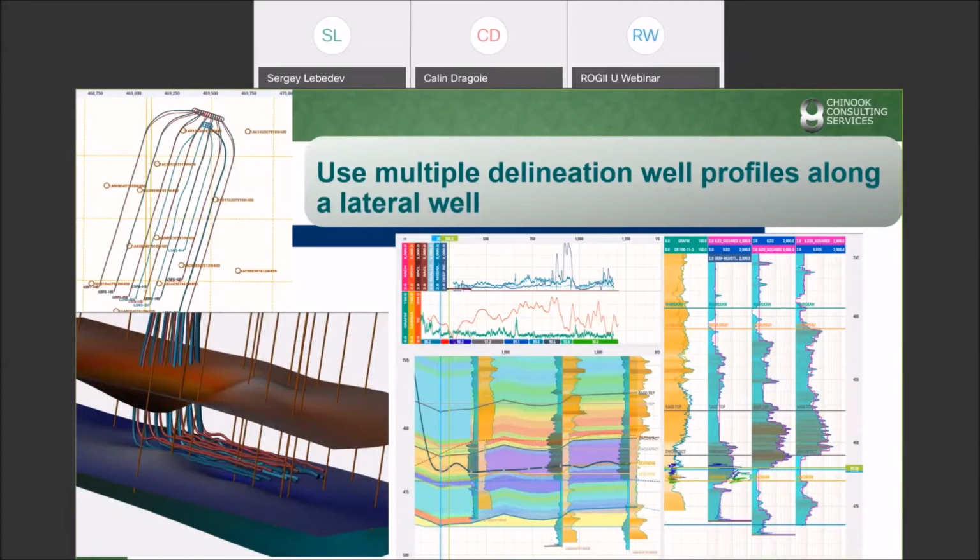The workflow that we developed leverages this ability by projecting multiple type wells onto the cross section and using combined models to simulate one single set of resistivity responses. And then, of course, comparing the simulated curves with the LWD readings in the graphical interface. That would be our regular geosteering interpretation. What we always want to do there is determine the stratigraphic position and apparent dips. In this particular case, when we're talking about the SAGD reservoir, we want to determine the standoff to water, and in addition to that, the reservoir trends at the well scale.